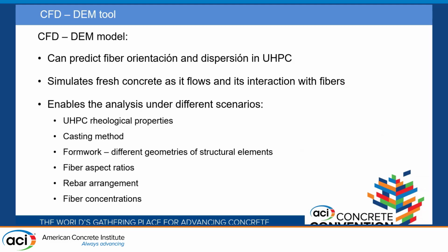With the CFD-DEM model, we should be able to predict the fiber orientation and dispersion in the UHPC, simulate fresh concrete as it flows and interacts with fibers, and also, with the DEM, see how fibers interact with each other as we increase the concentration. That will enable us to study all these different factors that affect the fiber orientation.